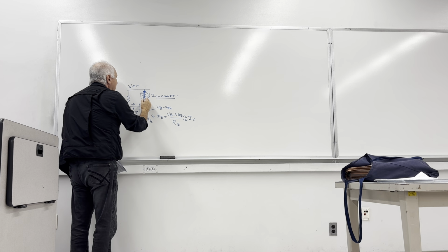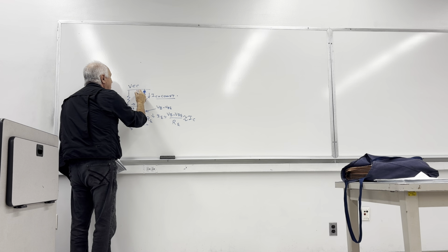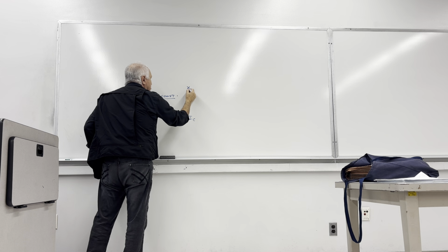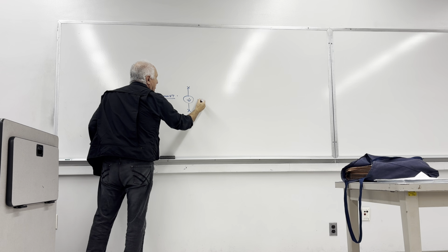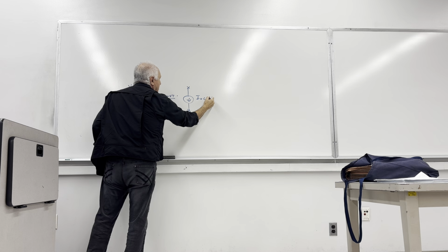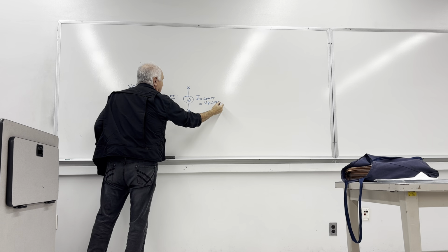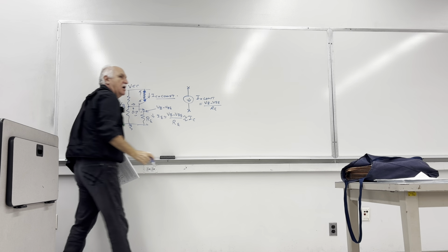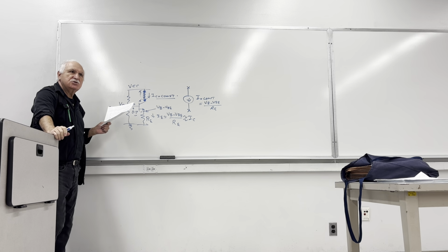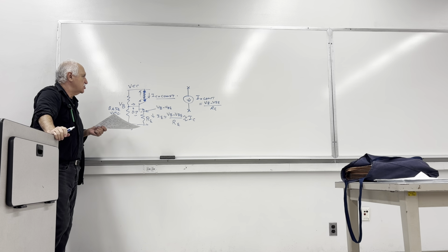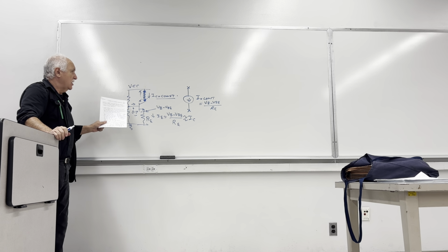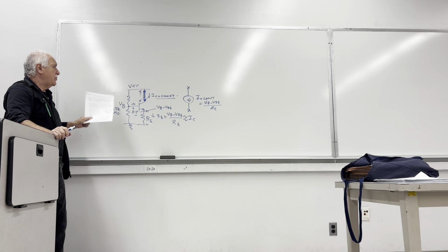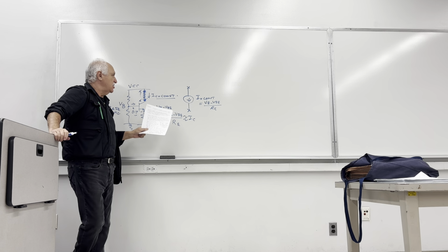Between these two points, X and X, you have a constant current. You have I constant equal to (VB minus VBE) over R. Okay, so apparently this is a very good approach, and it is indeed a very good approach to generate a constant current. But there's one property of the constant current when it comes to the application.